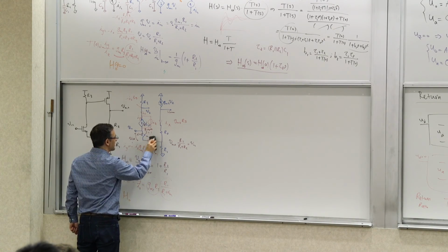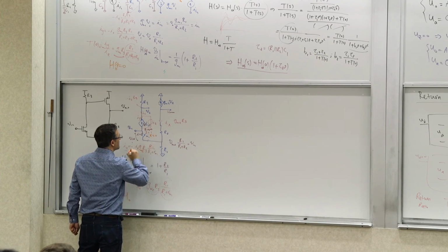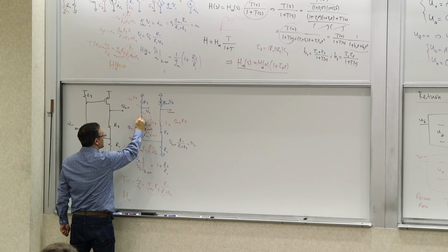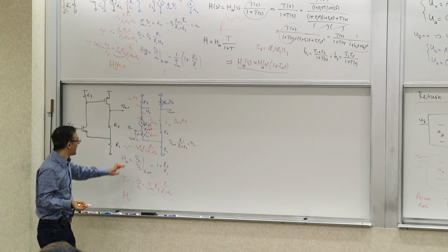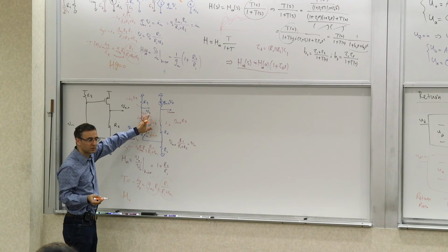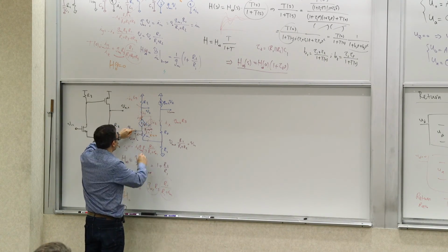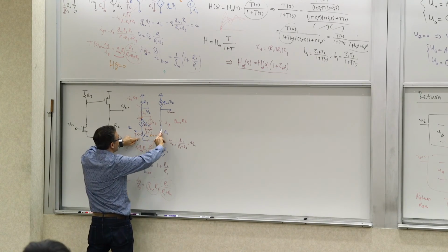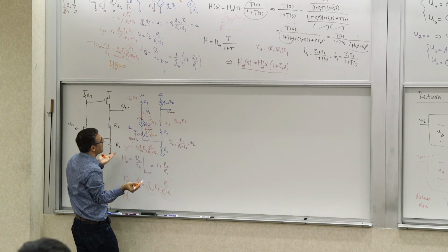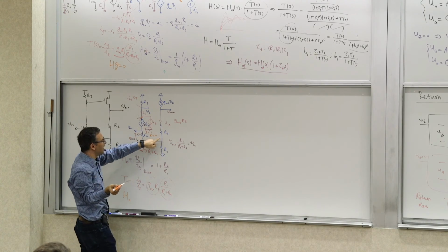So there are three calculations happening here. With K equals 0, basically this guy is gone. This is not there. And that one, of course, is not there. That's only for the return ratio calculation. So that path is gone. The only way the signal can get from the input to the output is through here. But there is a way for the simple input signal to get from the input to the output, right?